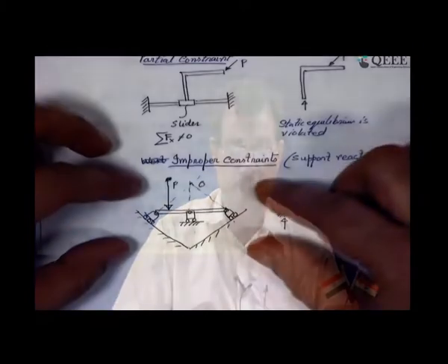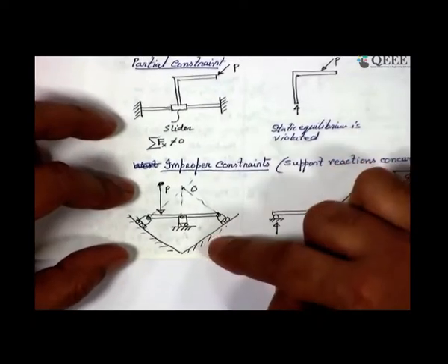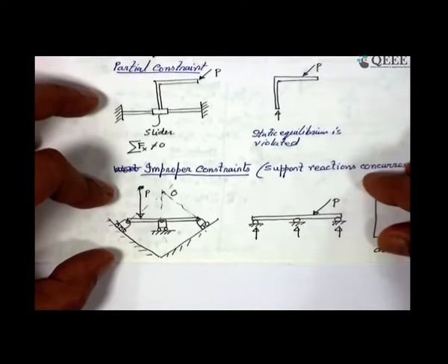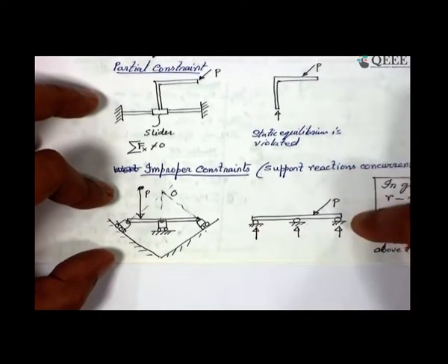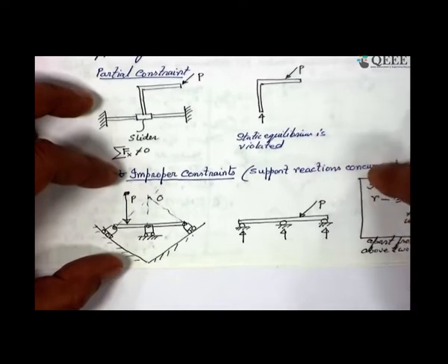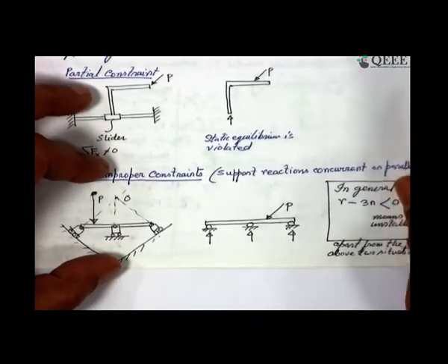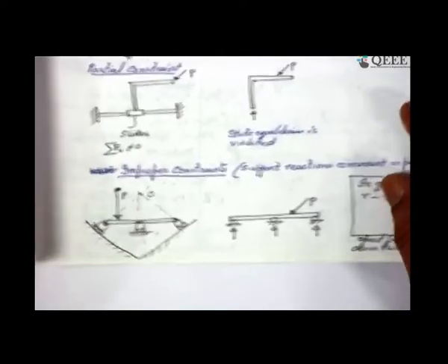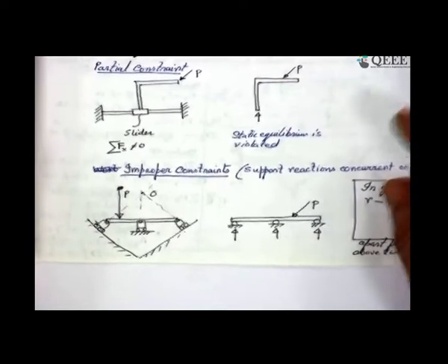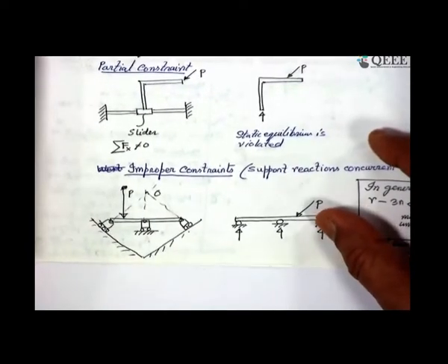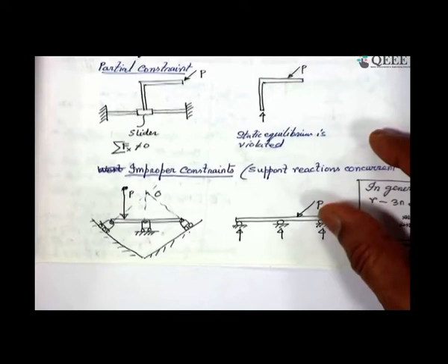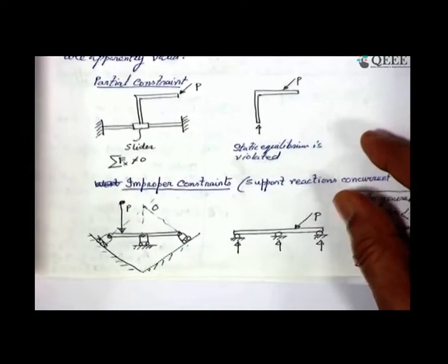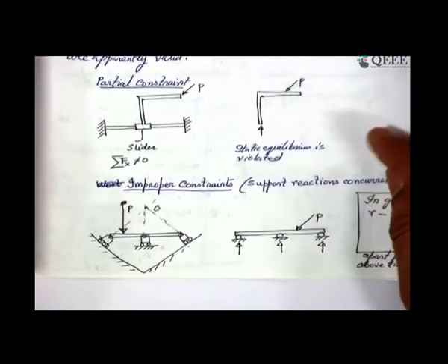For example, even if the calculation shows that structures with 3 rollers, or a beam sitting on 3 rollers, are stable as per the calculation, they may actually be unstable. It appears to be stable, but it is not, and the equation is satisfied even if they are found to be statically determinate. The question of finding out determinacy does not arise if the structure is unstable.